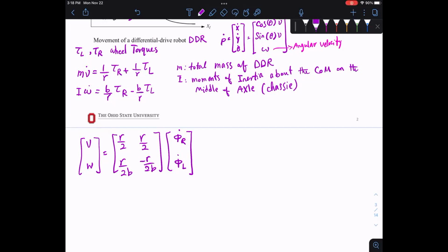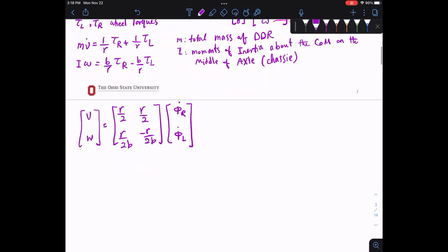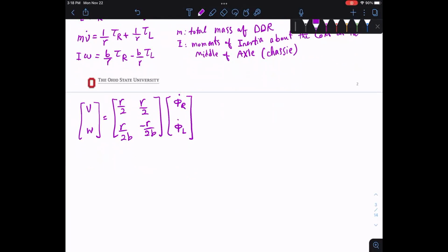So here we have inertia. And so we are here using the moment, actually. Not using kinetics, just using Newton's law, but you could use kinetic energy and then develop all of that. And then if you calculate V dot and omega dot, these are useful if you are using mobile robot control. You can always use these equations. That's why I brought it here. Tau R, tau L.